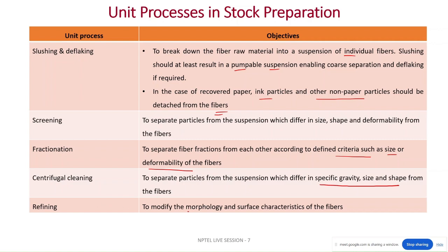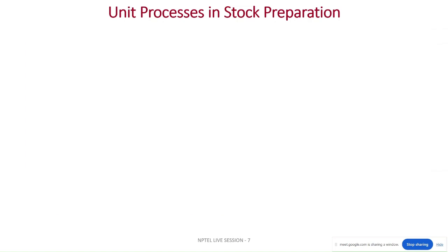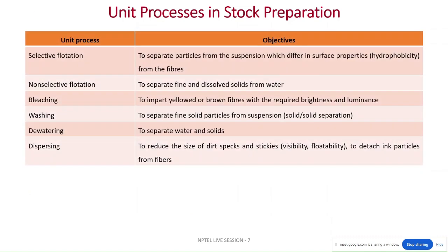Refining is to modify the morphology and the surface characteristics of the fibers. Also, there is selective flotation to separate the particles from the suspension which differ in surface property like hydrophobicity from the fibers. Non-selective flotation is to separate the fine and only the dissolved solids from the water.